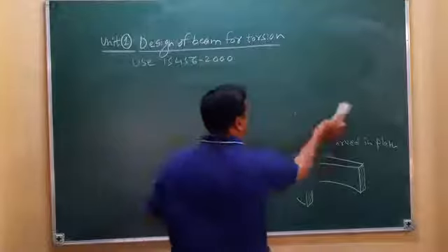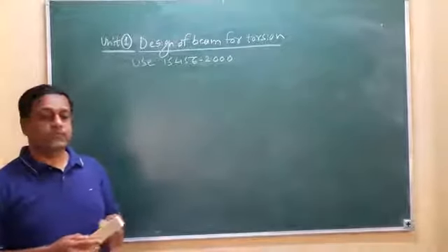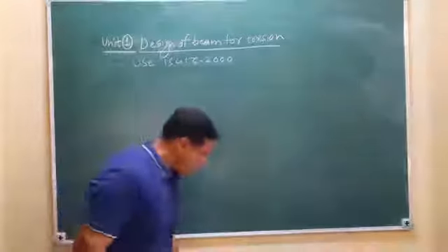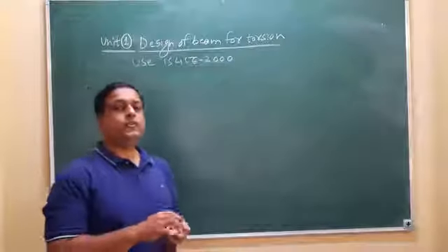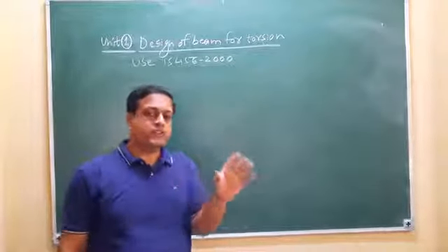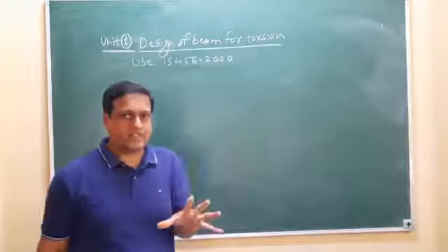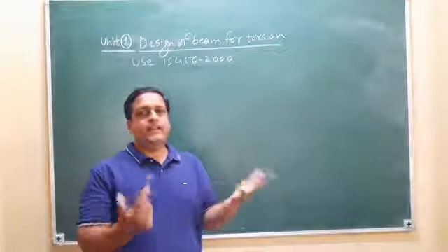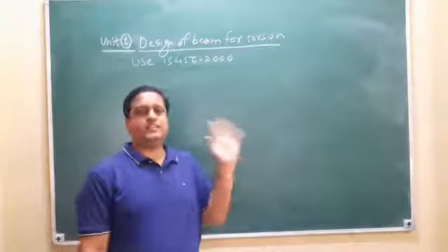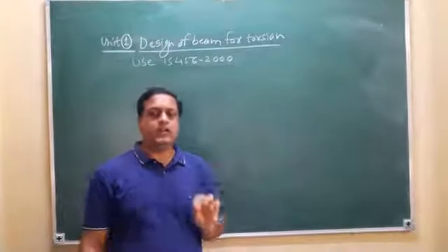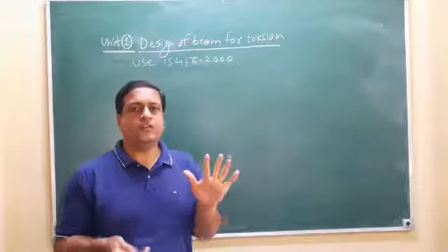Next is, what is the effect of torsional moment on a beam? That part I am going to tell you now. Already I have told you that due to the effect of torsional moment, there is development of extra shear force and extra bending moment. That extra shear force and extra bending moment you have to consider and finally design the beam. Whatever you followed last semester for design purposes, the same thing you have to do here, but you have to consider the extra amount of shear force and bending moment due to the effect of torsional moment.